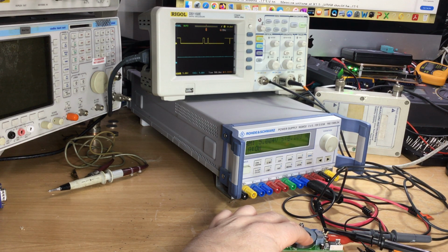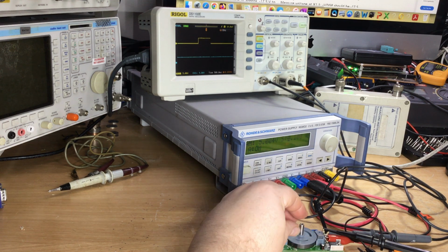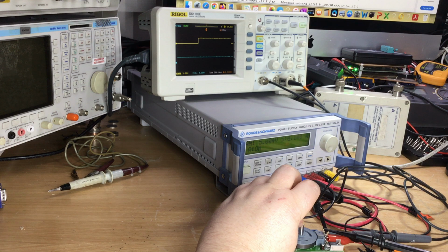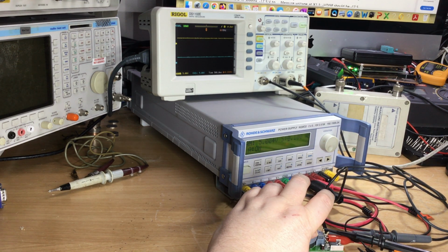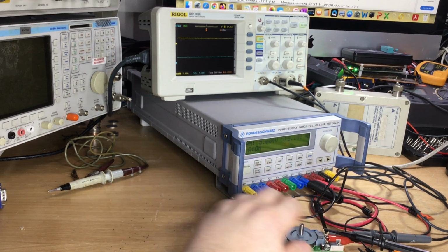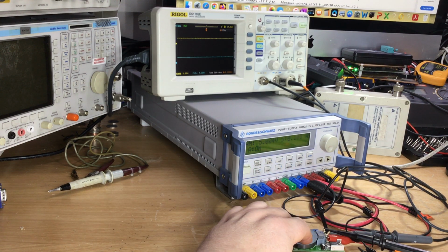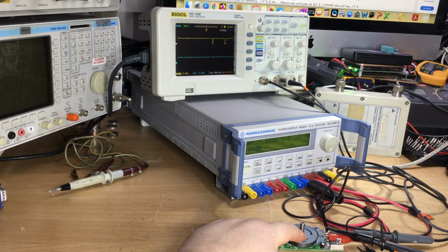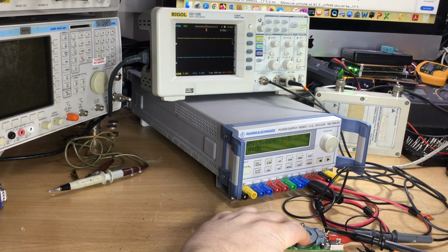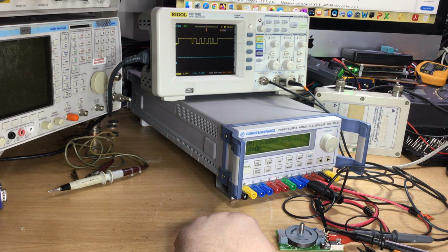do weird things. So this goes back to the original fault symptom, where if you grabbed hold of the spindle, the knob, and pulled on it or pushed on it while turning, it seemed to make the fault go away and come back, and you could adjust how accurate it was, or at least try and get it to work. So you can see there, just by pressing on the magnetic wheel, that it's already causing instability in the sensor.